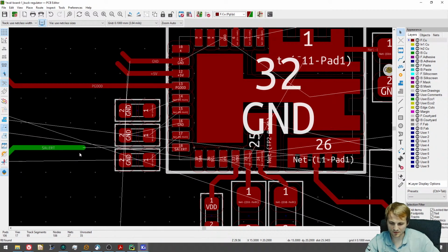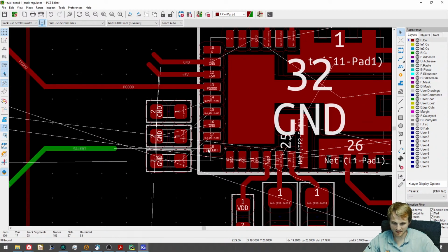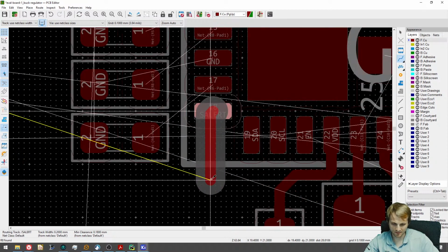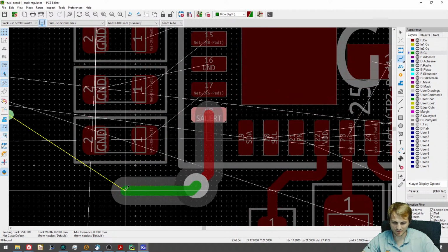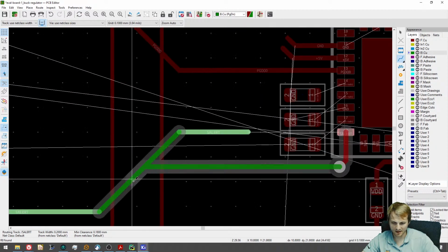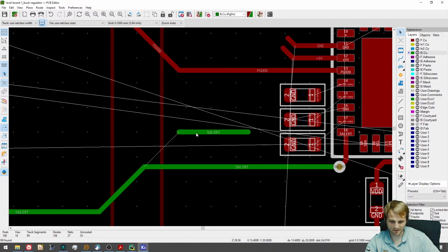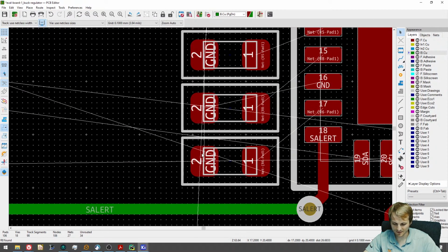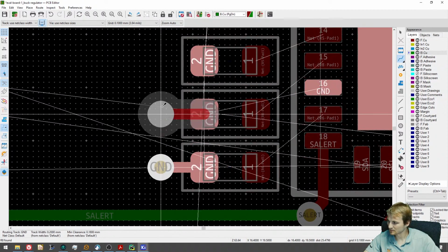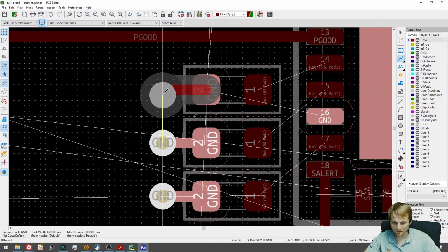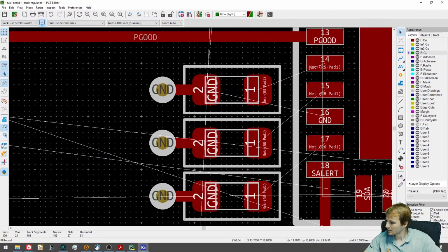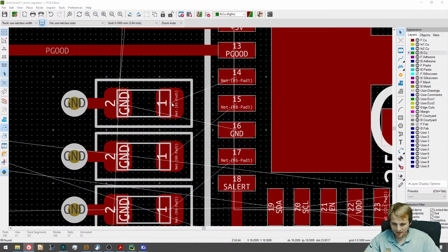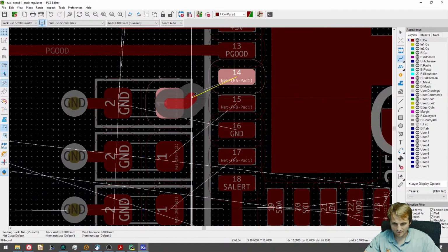And now we can move S alert. And since now it's a four layer board, we don't really have to care about trying to keep lines on the top layer. So once we drop a via down for saving a via, if it's going to an output connector, we'll just keep it. There's no purpose not to, or no reason not to. Okay, now we can add these traces.